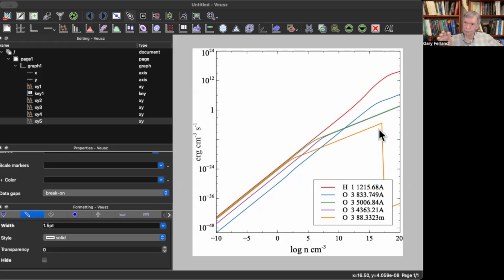Setting up the sim had a couple of tricky bits. A few new commands were introduced. Then I disabled some physics because I wanted to keep it very, very simple. In a real calculation, you would leave all the physics alone. You want Cloudy to include all of its physics. But this shows the simple case of a pure collisional model. We turned off induced processes. So it's only a collisional model at a given temperature and a given level of ionization. The only thing varying is the density.